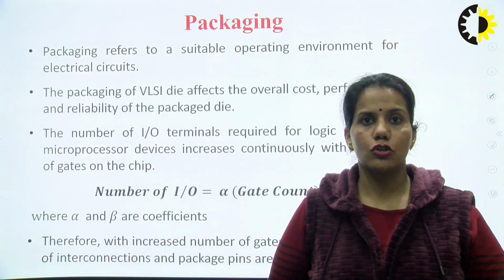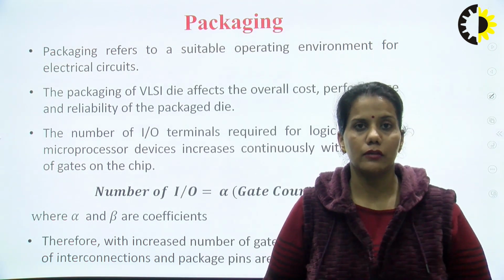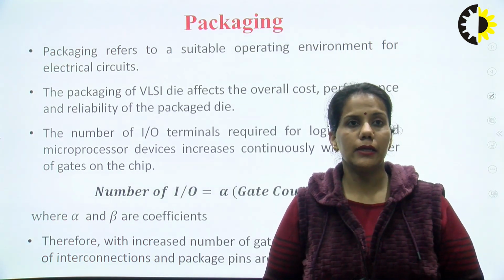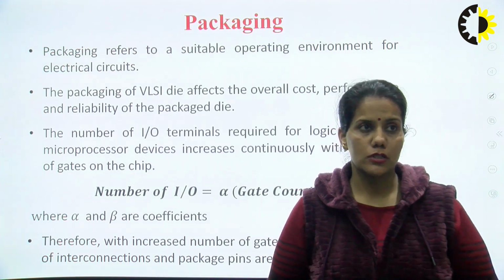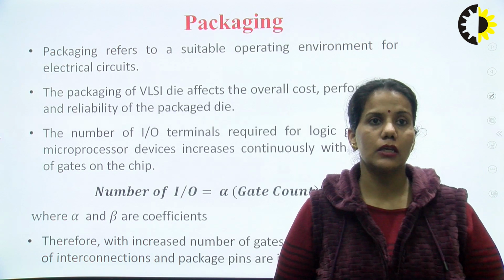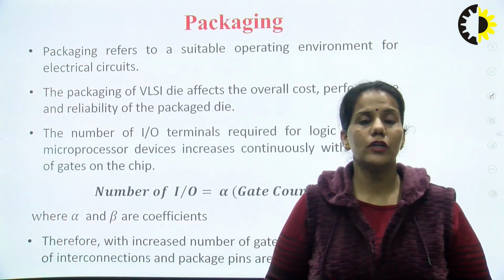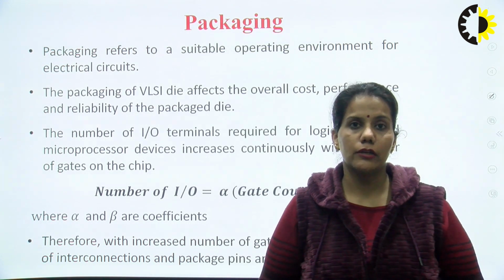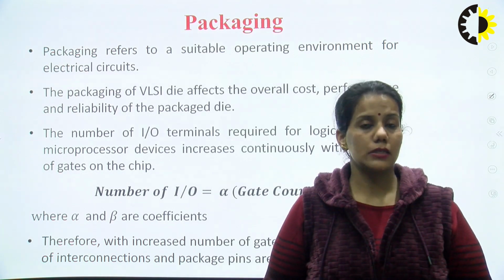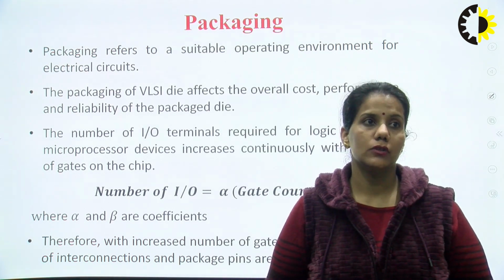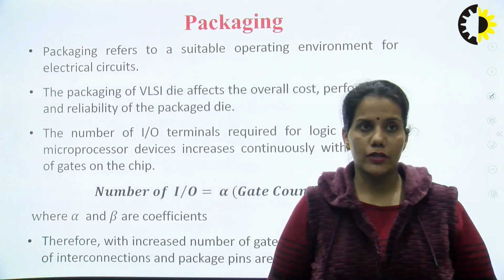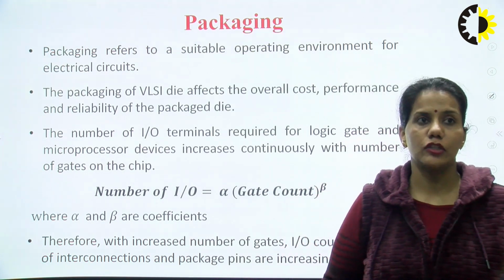The packaging of any integrated circuit should be so reliable that the heat dissipation caused in the IC should have a proper sinking capability. So if we are not providing a proper package to an integrated circuit and it is getting heated up so fast, it means that the packaging is not good enough. So we can say that packaging of VLSI circuits affects the overall cost, performance and reliability of the packaged die.